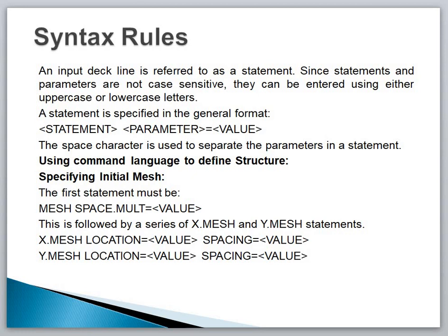Using the command language to define the structure. Specifying the initial mesh, you first have to write mesh space.mult equal to value. This is followed by a series of x.mesh and y.mesh statements: x.mesh location equal to value, spacing equal to value; y.mesh location equal to value, spacing equal to value. Let's go to the code.